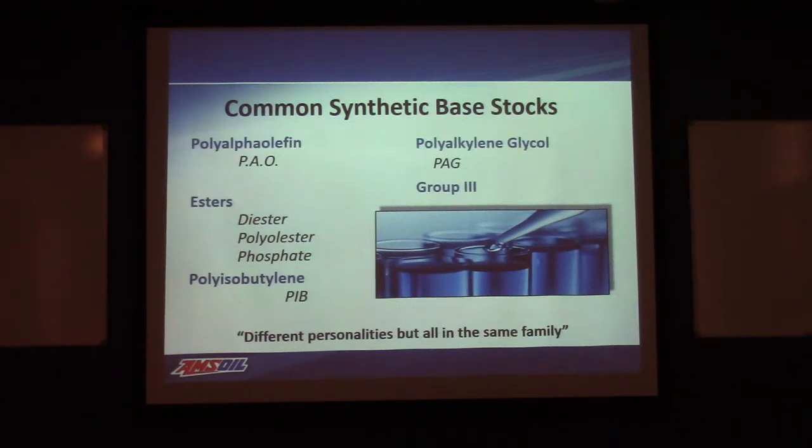Again, I mentioned that when we're dealing with lubricants, the term synthetic is very general. It refers to a wide variety of fluids, okay? They're not all the same. They don't all have the same performance characteristics, but they fall in this family of groups. Probably the most dominant ones that you see out there today, first one in the upper left-hand corner, is polyalphaolefins, or PAOs. We see them heavily used in the production of engine oils, so on and so forth.